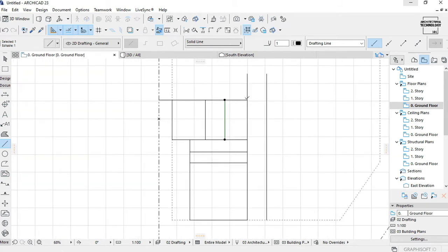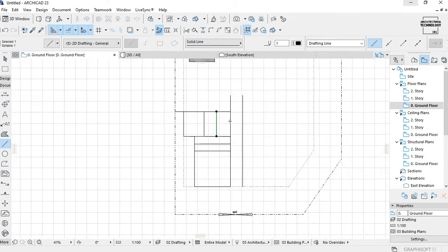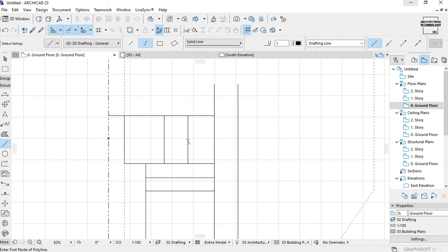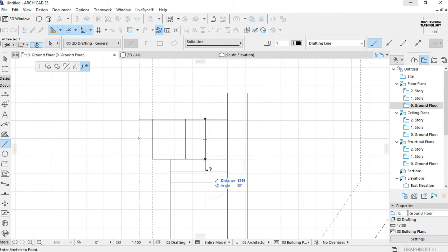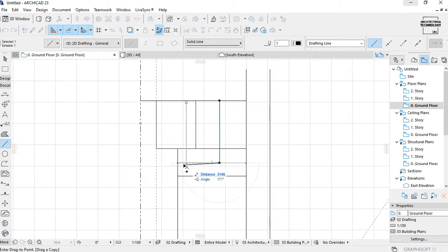So we know our staircase is here, right? We know for a fact our staircase is there by what we've designed. So we want to leave enough space for a lobby. 1345 is okay, is enough space. Maybe we cut it off once so that we create a little bit of a lobby space from the toilet powder room. How big is this? This is 3.960. Maybe we take 1.250. That should be enough for you to open a door.